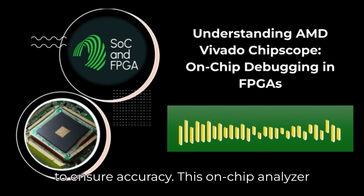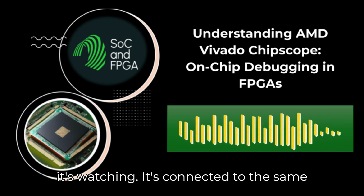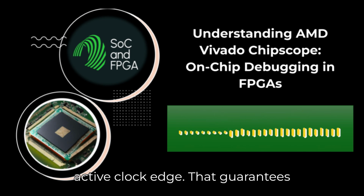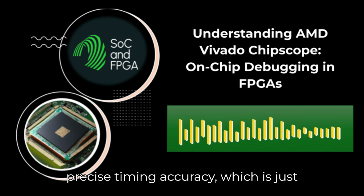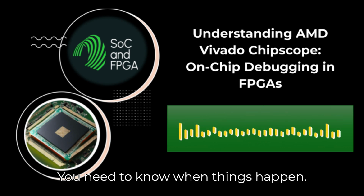And to ensure accuracy, this on-chip analyzer operates synchronously with the logic it's watching. It's connected to the same clock domain, sampling signals on each active clock edge. That guarantees precise timing accuracy, which is just paramount for digital debugging. Right. You need to know when things happen.